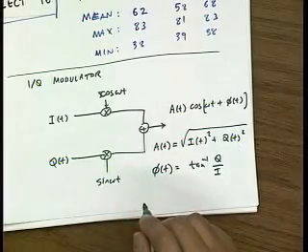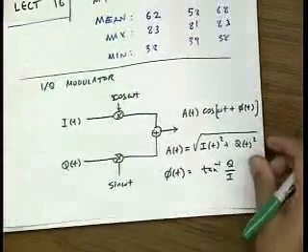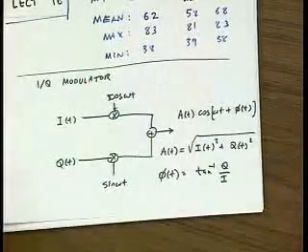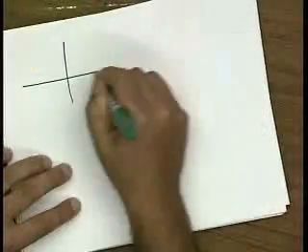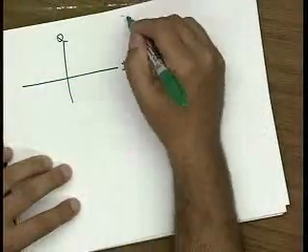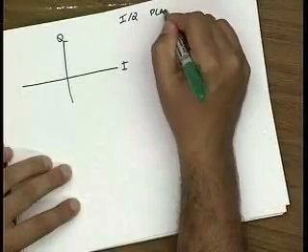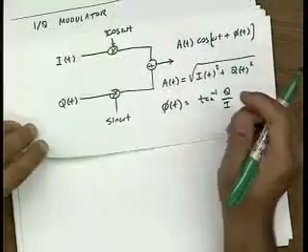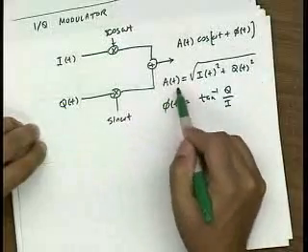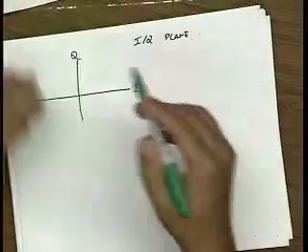And there's a nice graphical interpretation for this. We can plot I and Q separately. They're orthogonal from one another. So this is the I, this is the Q. Again, this is the IQ plane. And if, for instance, I want to modulate my signal in such a way as to keep the amplitude constant, that corresponds to a circle on this plane.